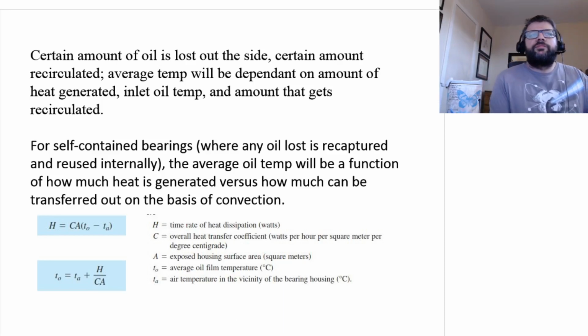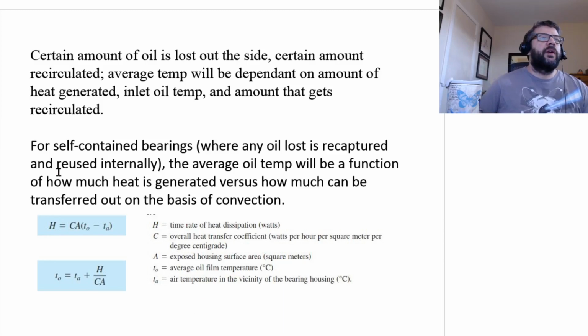So for self-contained bearings, we don't have recirculation; we're not feeding it oil at a particular temperature that we've had a chance to cool. That's the good thing about the non-self-contained bearings, that we were able to actively cool the lubrication oil.